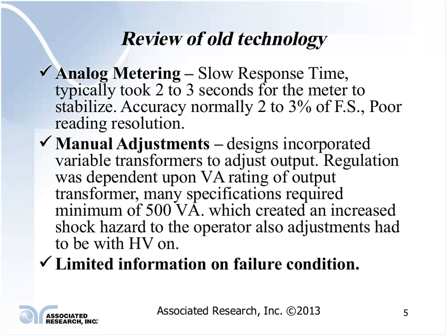let me run through this real quick. Sorry about that. So 5,000 volts times 3 percent, 0.03. Okay, that's 150 volts. So anywhere along that scale, my accuracy could be plus or minus 150 volts of that reading.